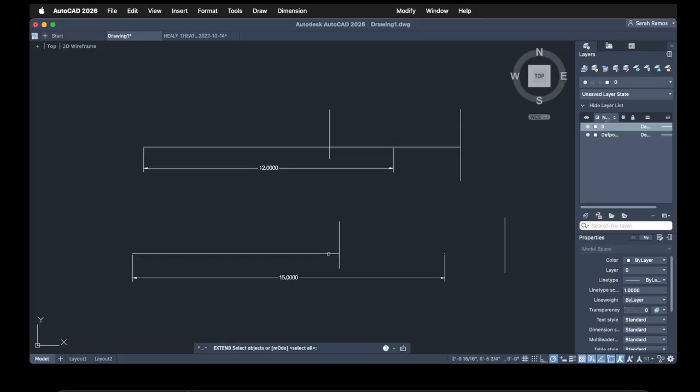Instead of interpreting the behavior automatically, AutoCAD is waiting for me to set the boundary. I have to click on this line to tell all relevant lines to stop over here. It adds an extra step that allows me to control and set the boundary. That is what it will look like on my screen. TR, spacebar. Trim works the same way. I have to tell AutoCAD my specific trim line before it does anything.